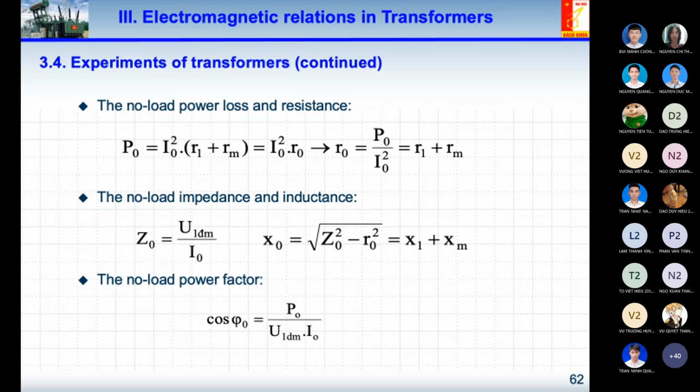That's the reason why the electricity company wants clients to work with a high power factor and not a small power factor. When the transformer is connected to the full load, it is okay, but with a low load, I think it's not okay. In addition, when the transformer is working with a low load, the efficiency is not very high.